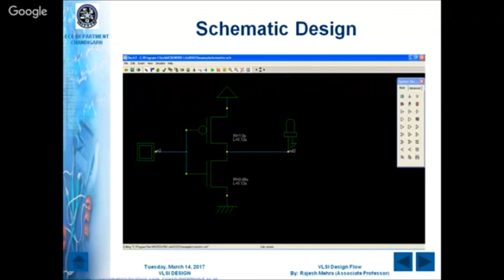Optimization will not be there, and you can say it is difficult to modify. Second option is semi-custom design. In semi-custom design, what we use are internal inbuilt ready-made transistor layouts from the library, but we try to manually route it. We route it from our own side. So routing is from our side, we try to optimize the routing part.